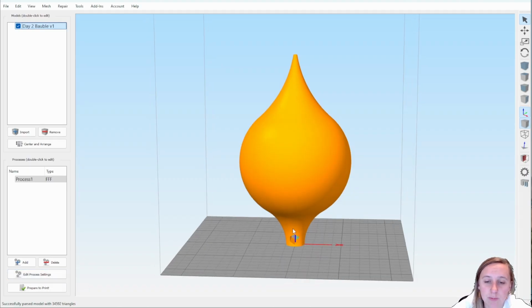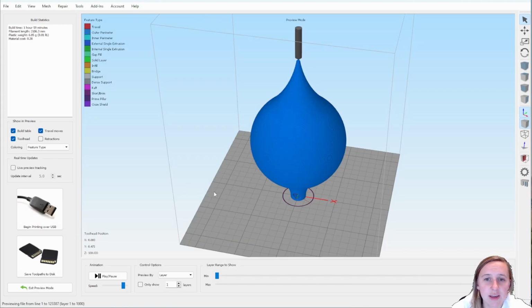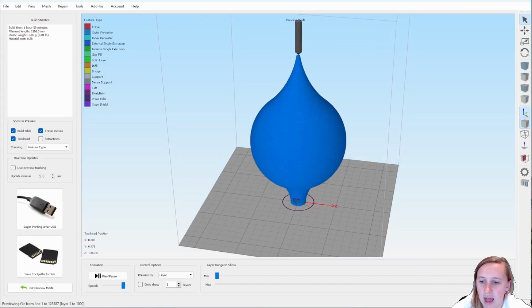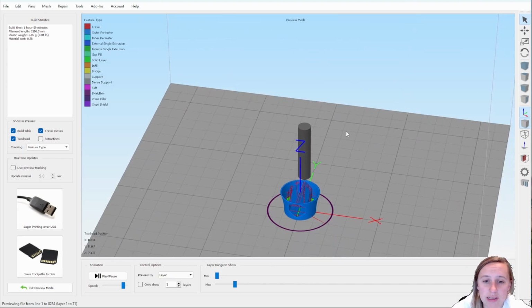But you don't want this bottom section to be a vase mode. So set your vase mode on your 3D printer, and this will mean it will spiralize the whole of the outside contour in one continuous path. However, you want to print the bottom as a solid section.